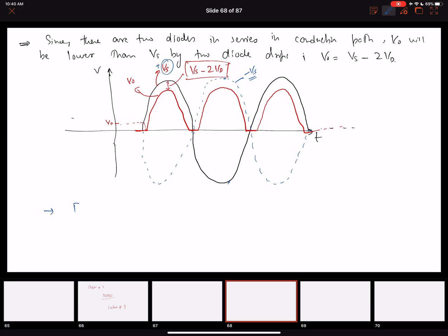It's a full wave rectification, one important thing to remember. And the second thing, output voltage has a 2 times voltage drop in the peak value. Now if I compare this with the center tap again, in the center tap, we had 2 diodes. Over here we need 4, but 4 is pretty easy to come by.